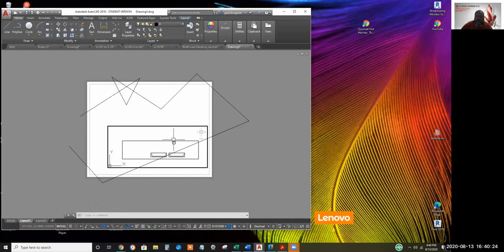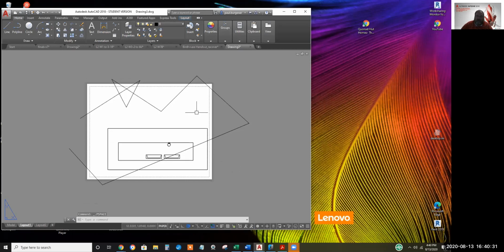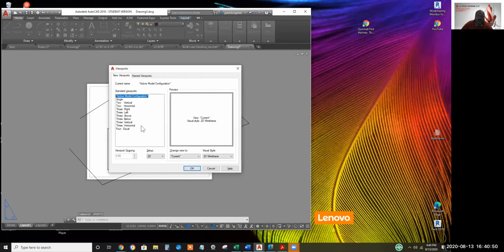Anyway, getting back to the exercise, let's say there's the floor plan of our mobile home. I'll double click and I'll make a second viewport that shows a close-up of the sink right here. I typically copy the viewport, but you can make another one. I think vport is the type in, or mview is another type in. Anyway, you can make a single viewport this way.